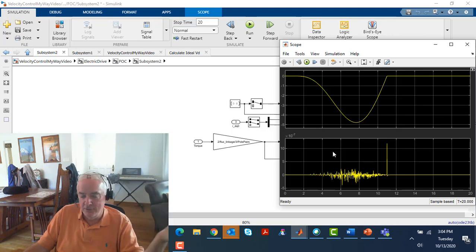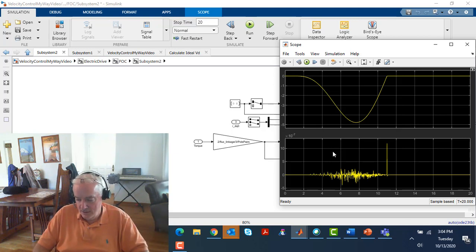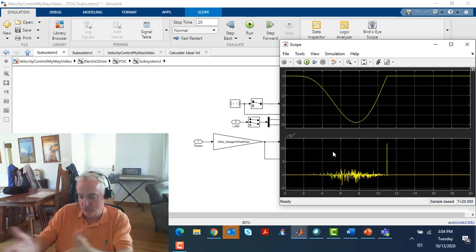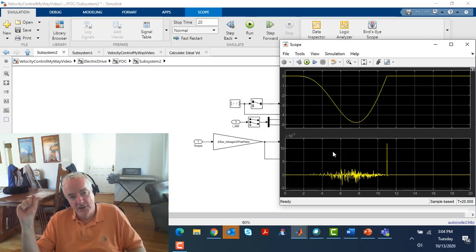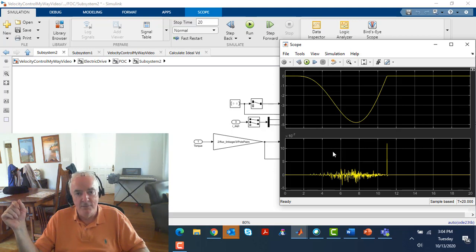the inductances and resistances, and essentially, I'll call it, the description of the equipment. Okay, and so if things still go unstable even in a simulation, it really means that you are not accounting for the unknown. And if it's a simulation, the unknown is minimal, right? The true unknown on this one is essentially a numerical error that takes place in our calculation of various numbers, that's on the order of 10 to the minus 16th.